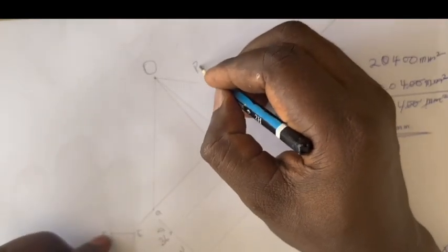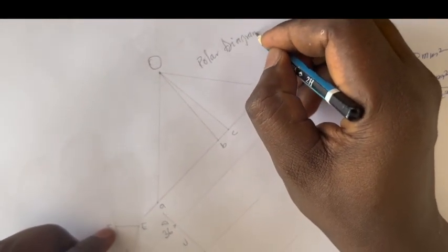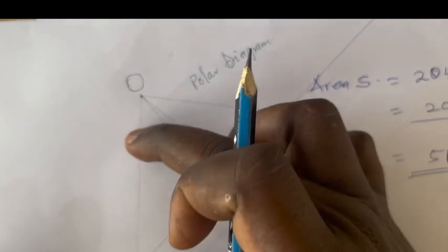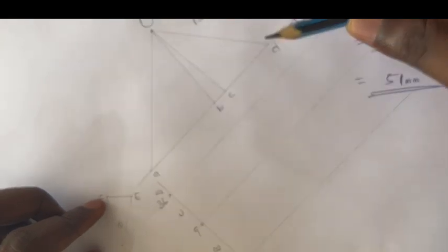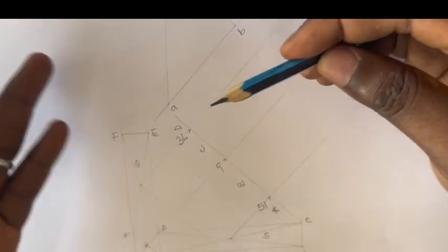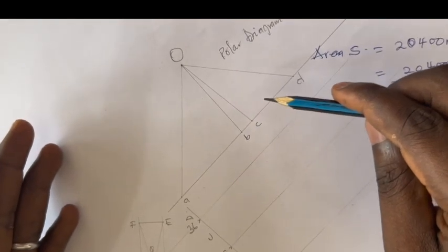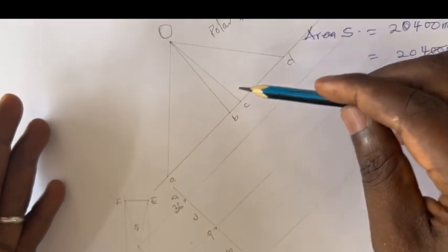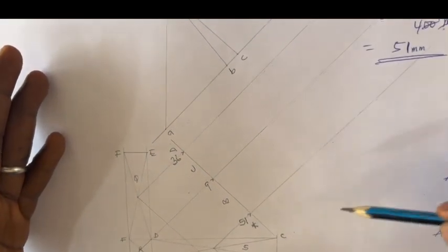So we can say this is the polar diagram, right? So I'll be using this to draw my link polygon. And when you pick these, you pick lines that are parallel to them to bridge their gaps, right? When I look at this, we have A behind here, we have B here, we have C, and D also is behind, right? So it will not be appropriate to start from A and D, but rather it will be good to start from B and C, because that will give us the chance to bridge the gap between B and C.